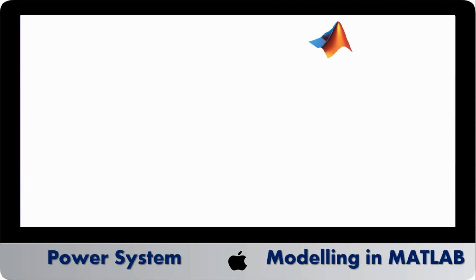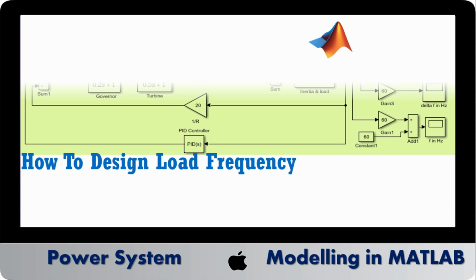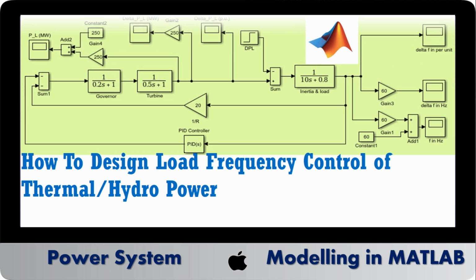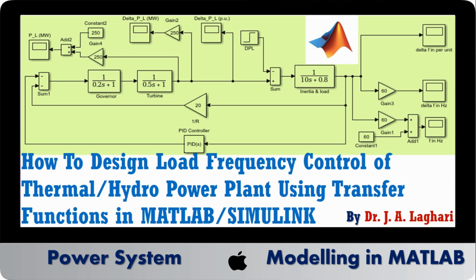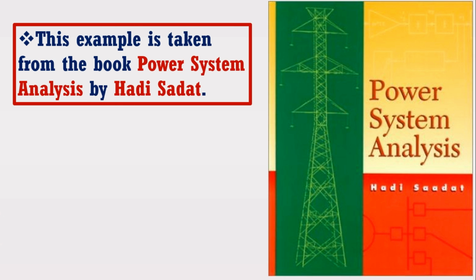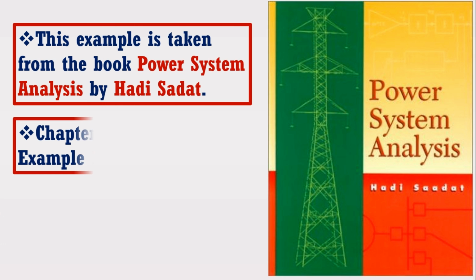In this tutorial I am going to teach you how to design load frequency control of thermal or hydro power plant using transfer functions in Matlab Simulink Software. I have taken an example from the book Power System Analysis by Hadi Sadat, Chapter 12, Example 12.1.